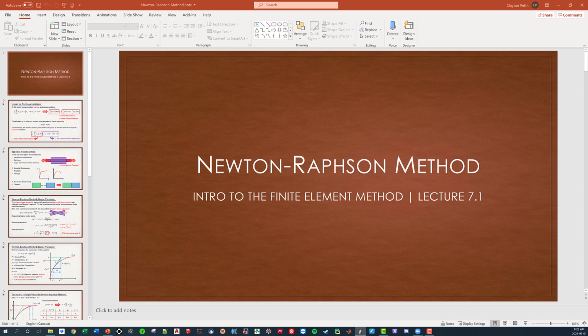And again, you guys may be always confused what exactly is a traction vector. Well, let's switch to a different color. That's if I were to have, let's say, a distributed load acting on our beam. So if we had this distributed load right here, what that traction vector does is it takes that distributed load and creates 2 point loads at our nodes. So those come right from that big ugly formula that we're so used to seeing. That N transpose times rho b and then N transpose times t_n. That's something you guys have seen.